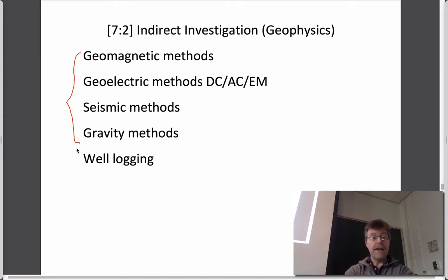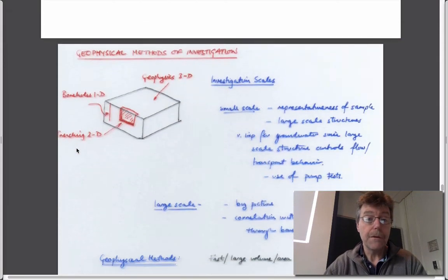known values. And in seismic methods, we use the acoustic impedance, which is the product of density and, most significantly, the seismic velocity, the speed of sound in rocks rather than the speed of sound in air, with which we're communicating now. And gravity methods measure the change in the gravitational traction of the Earth by things like voids. So if you're standing on top of a big tunnel, then you can sometimes sense the change in gravity, not yourself, but by using very accurate methods of doing that. So those are all things that are prosecuted, if you like, from the surface. And well logging are the same kinds of geological measurements, but are done in the boreholes that you might have drilled in the things we've talked about in the past. So that's really what we're talking about.